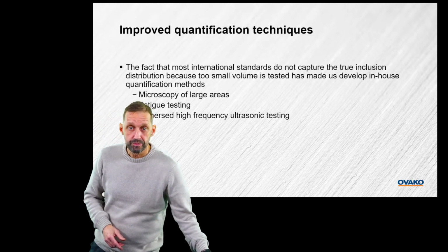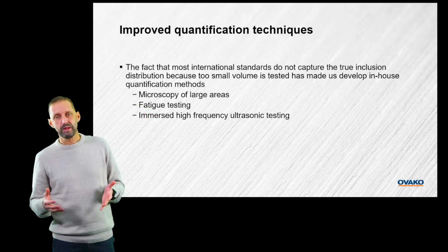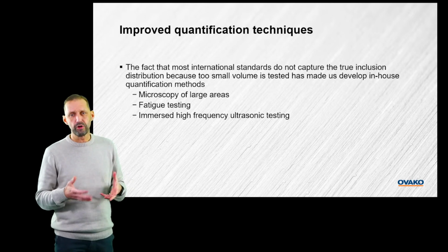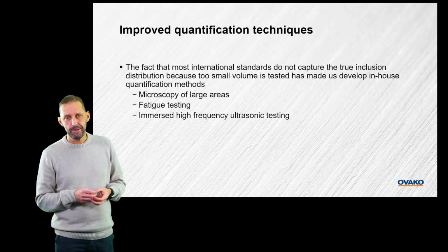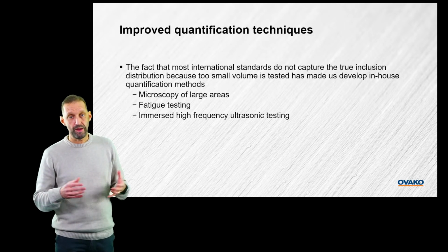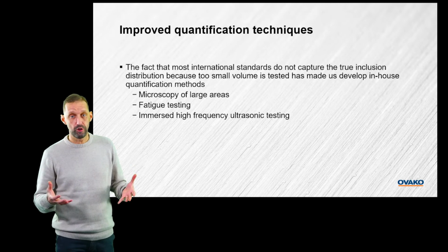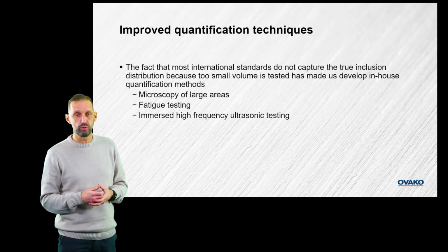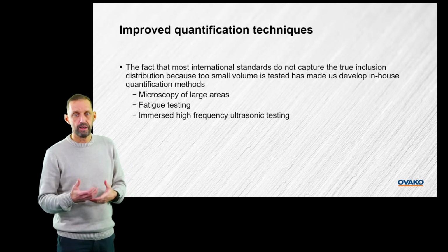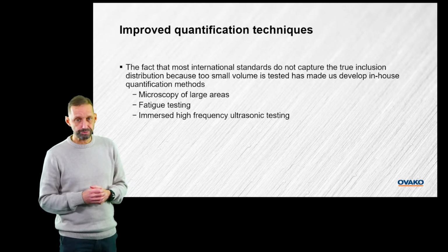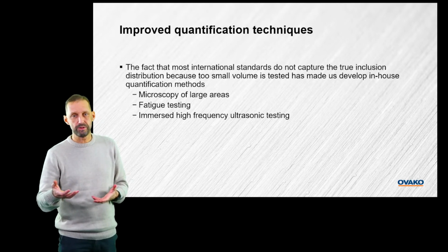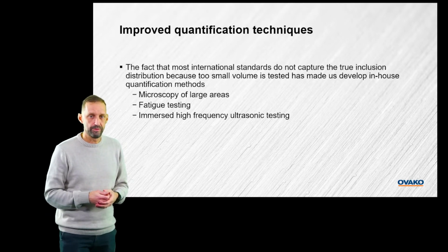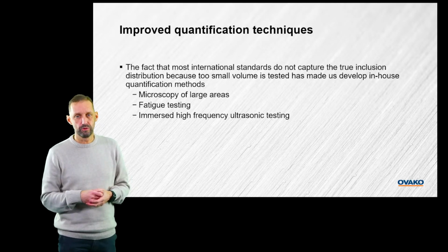So it's excellent. But we also now see the opening of working much more with immersed, very high frequency ultrasonic testing. We've been working with that for a long time. We have a very good method with 10 megahertz, taking a good way of discriminating between larger defects. We have that published on our website as well, so anyone can use it as their specification or standard and use that for sorting out.